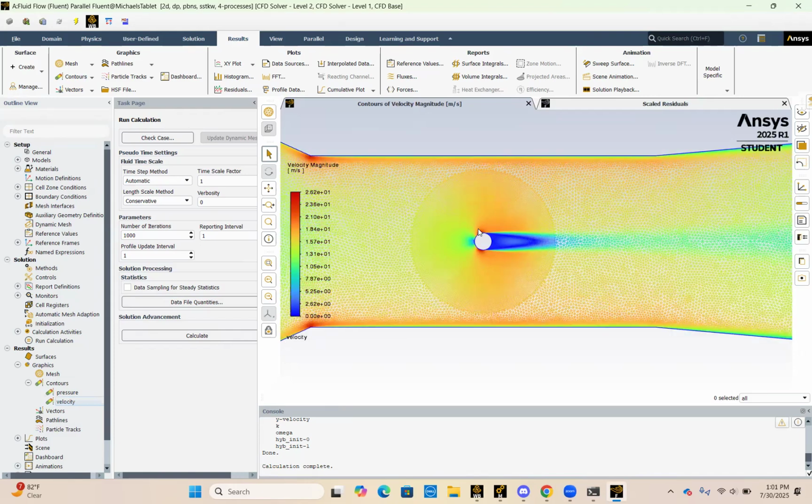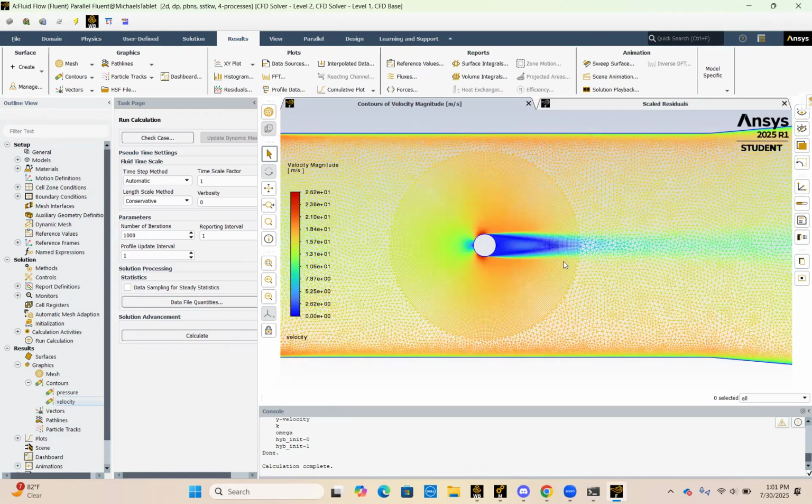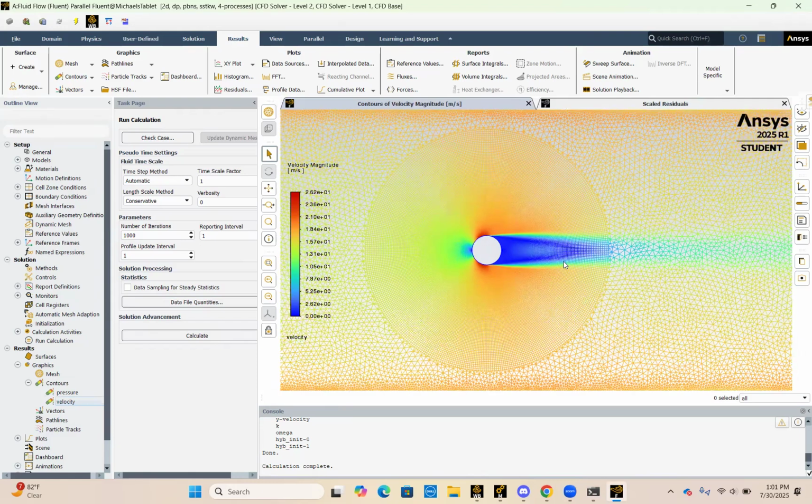If we zoom in a bit further, you can see where this inflation comes into play. If we were looking at this, it would not be satisfactory to really analyze the flow around the circle. This inflation is very important because we can see with more accuracy and detail what's going on. We can see our stagnation point where it's hitting the front, where velocity drops to initially zero, which is to be expected. We once again can see this dark blue band where there's the no-slip condition.